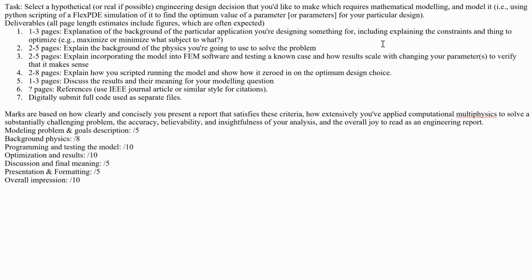So make sure that, let's say in the thermal strap example, if the width gets very large, then the temperature of the computer chip gets basically to the temperature of the reservoir. It stays at 20 degrees the whole time. Whereas if the width is very small, then the temperature gets too high. It gets above the amount that we wanted pretty quickly. So this is the kind of thing that you'd want to check with this. You can check edge cases.